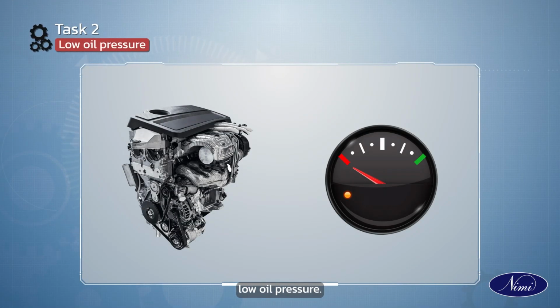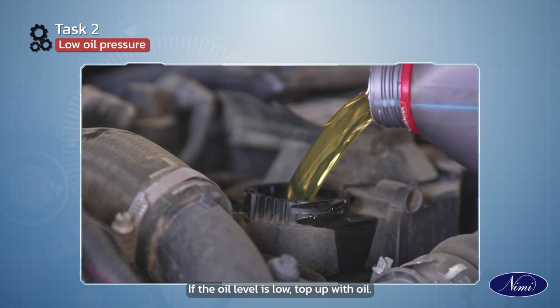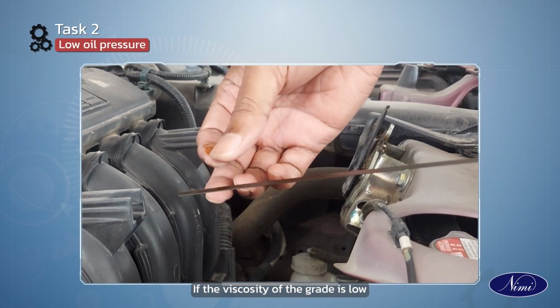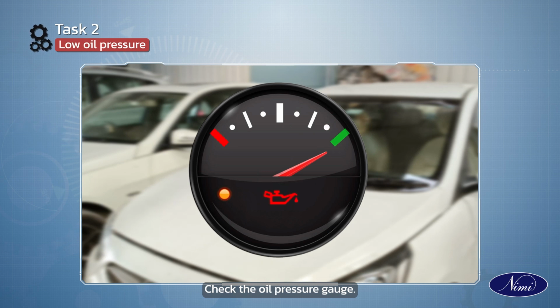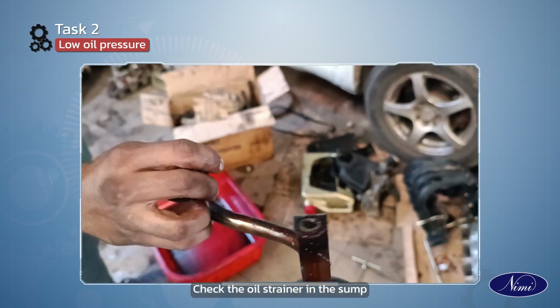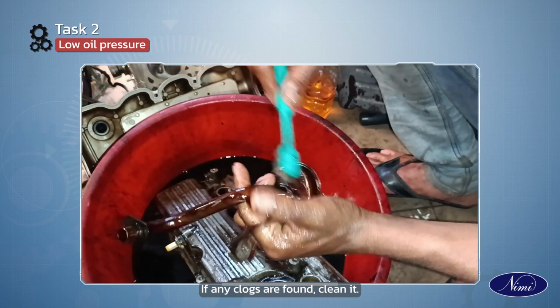Low oil pressure. Check the oil level. If the oil level is low, top up with oil. Check the grade of the oil. If the viscosity of the grade is low, replace it with the correct grade of oil. Check the oil pressure gauge. If the gauge is found to be defective, replace it with a good one. Check the oil strainer in the sump. If any clogs are found, clean it.